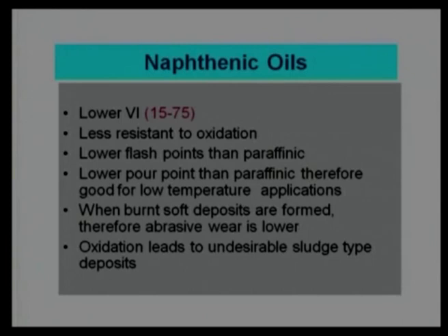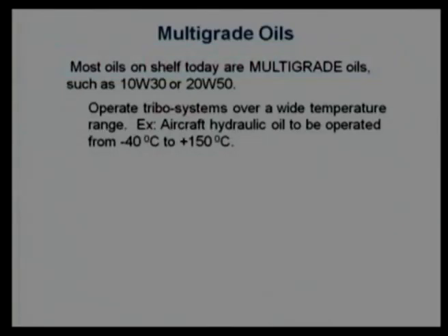But because of the deposits, and in addition when there is oxidation, they make sludge formation, clearance will reduce, operating condition will change, and that is undesirable. Continuing with the mineral oils: not very high VI, not very high viscosity index, more tendency towards oxidation at moderate to high temperature. We use multi-grade oils.